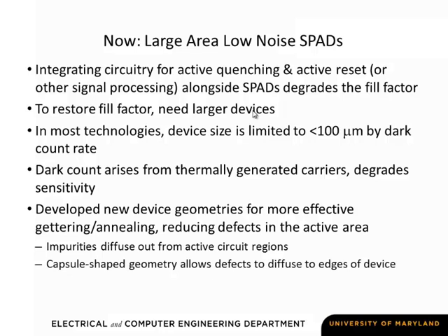In many modern SPAD designs that you see reported, the pixel size, the photoactive area, is less than 100 microns, significantly smaller than in a lot of devices. The dark count is always there, arising from those thermally generated carriers and degrading the sensitivity.